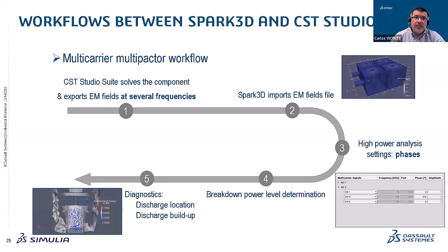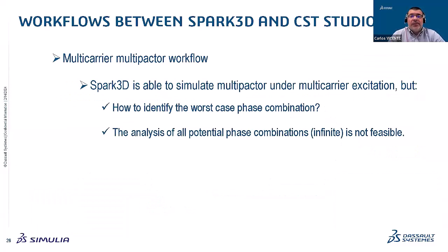Of course, there is one point here which is different from the single carrier case, and which is indeed critical. As said, you can perfectly run this, create your own multi-carrier signal and simulate it with Spark 3D. That's more than fine. The problem is that typically that may not be enough, because you need to identify the worst case phase combination.